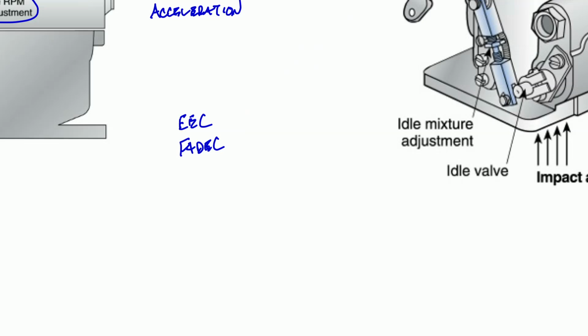As mentioned before, my procedures for inspection are going to be pretty similar. But one thing that we're looking at with turbine engine systems is most of them are not really adjustable out in the field. In most situations, if you have a real issue with a fuel control system, then you're going to be removing it and sending it out.